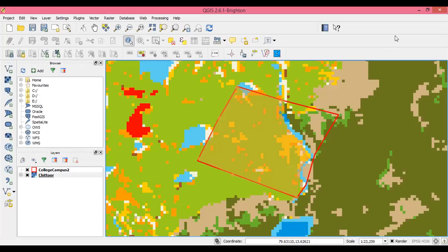The peak rainfall intensity of this area needs to be known. Okay, so for that you already have the rainfall data for some one given year, 2018, right? That data has already been shared with you when you did the first project number 1. So using that, you will go into that data and try to find out which is the nearest rainfall gauge to this location that you have selected, right?